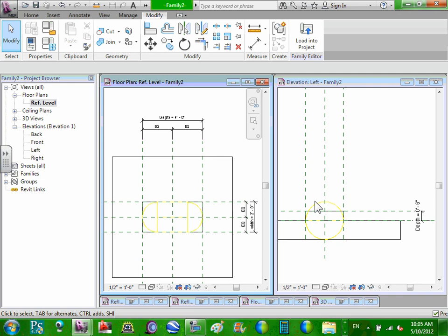and the thing that you have to remember, you'll catch this as you gain experience, is that no matter what the computer says, when you run lighting calculations, or if you run power calculations, and it says you need this, it still has to pass the smell test. When you do a project like this, if it comes up saying you need a 400 amp service, that doesn't feel right. And you can say, yeah, but this is what the computer says.